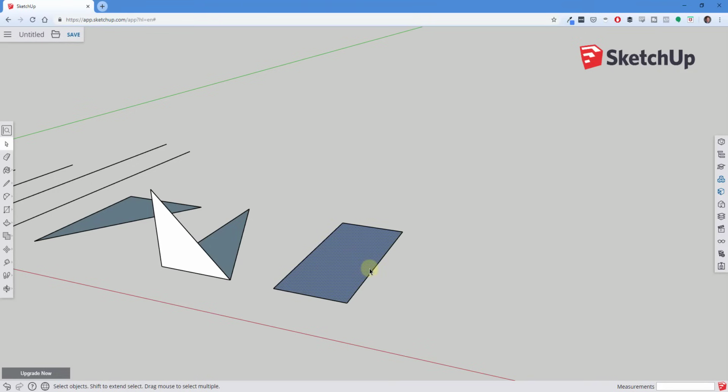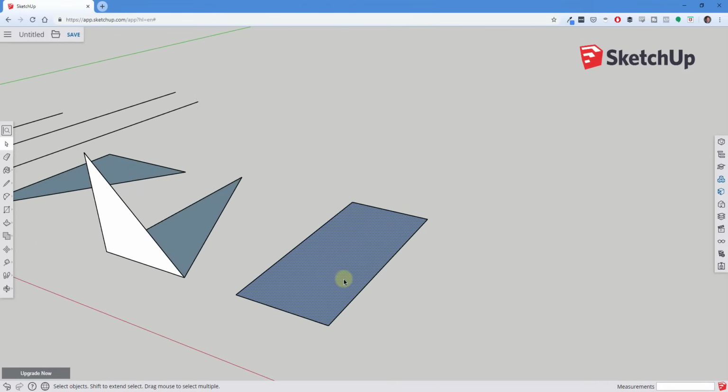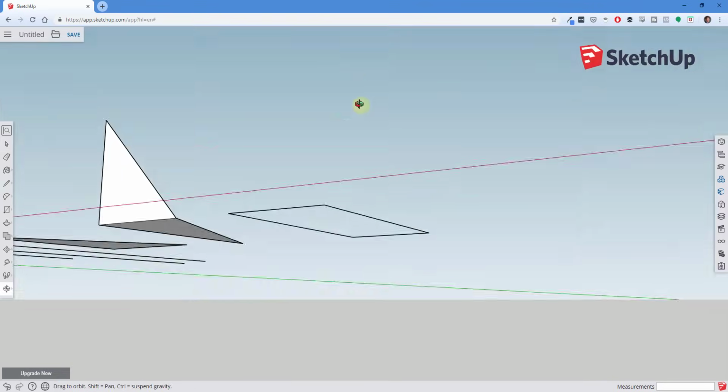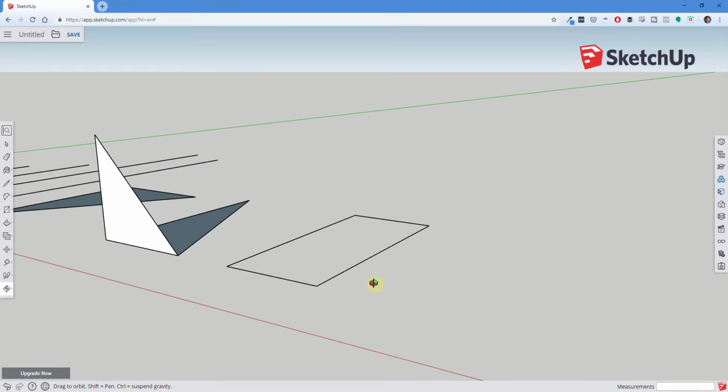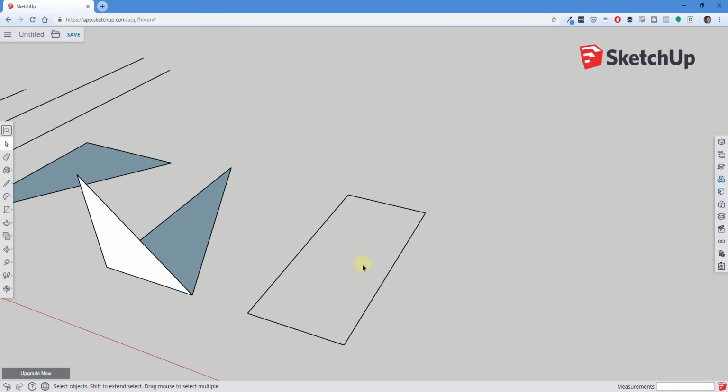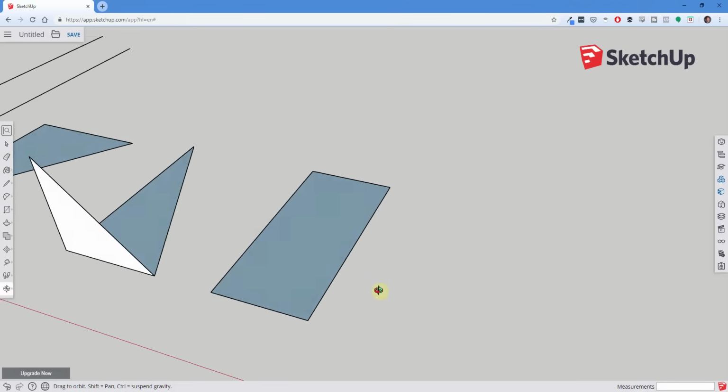Another thing to note is that sometimes with a face like this one, you can select it, and you can see this is indicating that it's selected because you get all of these little dots in here. Usually things turn a bluish color when they're selected inside of SketchUp. Let's say this face got selected, then you hit the delete key to delete that face out. If you wanted to heal that face back in, you could just trace over one of these edges with the line tool, and you can see how this fills this back in whenever we draw that edge.